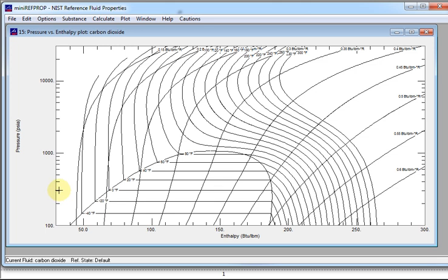Because our evaporator, we want it to be absorbing heat at 0 degrees F. Okay? The condenser doesn't look like it's going to even be a true condenser. It's going to be a heat exchanger where you're going to be exchanging heat, but it's not condensing. And it's going to be a very high pressure. And so what I want you to do is explore for me how to draw that box.